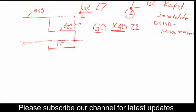So the tool will start running rapidly as it has read the G0 code. And it has to reach which coordinate? The destination coordinate is X45 and Z2. So the tool will reach this location with this feed rate. That is the meaning of rapid interpolation.